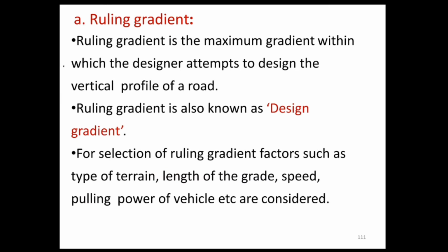The ruling gradient is the maximum gradient within which the designer attempts to design the vertical profile of the road. The ruling gradient is also known as the design gradient, and accordingly, the quantities of cut and fill are balanced. However, a flatter gradient may be preferred wherever practicable.